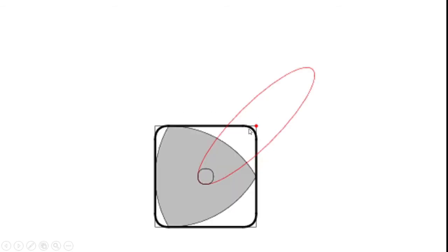I draw the square with unit length. I maintain the corners, so I can get the four corners. I put one corner as a center. I draw the ellipse with the minor axis and the major axis with the unit dimensions. In the center there are elliptical intersections available. I remove and trim the other parts not required from the center part of this Reuleaux triangle, so that I trim all other elements.